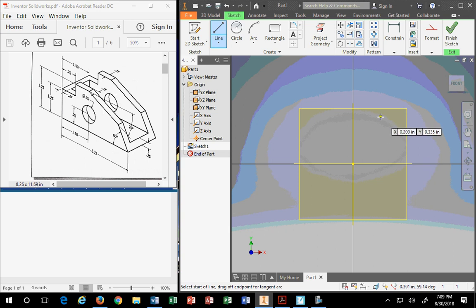I like to be grounded in the beginning of my model making, which means I really want my part to start at a known location. So I always want my initial sketch, my very first sketch, to be somehow related to my 0, 0 position, my XY 0, 0 position, especially if I'm a machinist. Then it's even more important because I'm a lazy programmer.